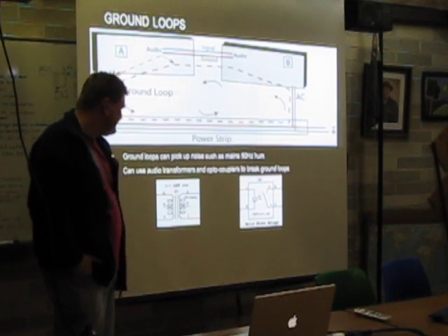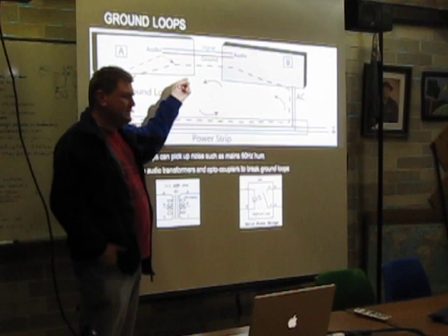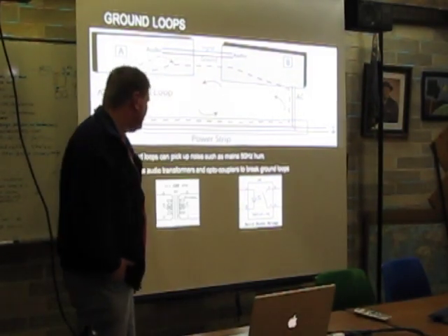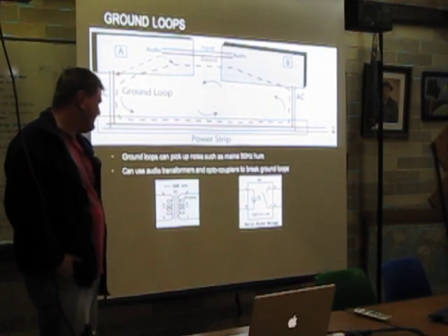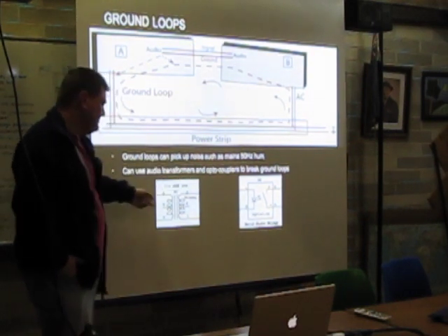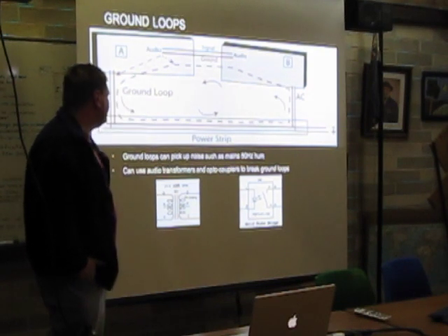It's just AC. And if you've got connecting up the PTT line in your radio, you can use an opto coupler solid state relay sort of arrangement. And those commercial interfaces often have this type of circuit inside to make sure you don't get this ground loop problem.